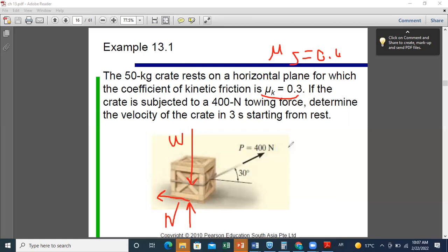So you start by saying, let us assume that we have a static friction. If we have a static friction, as you said before, there is no sliding between surfaces, and the ground is fixed, so the box is fixed also. So the sum of forces will be equal to 0, and the sum of forces as a vector is equal to 0. Now I decompose it into x and y.